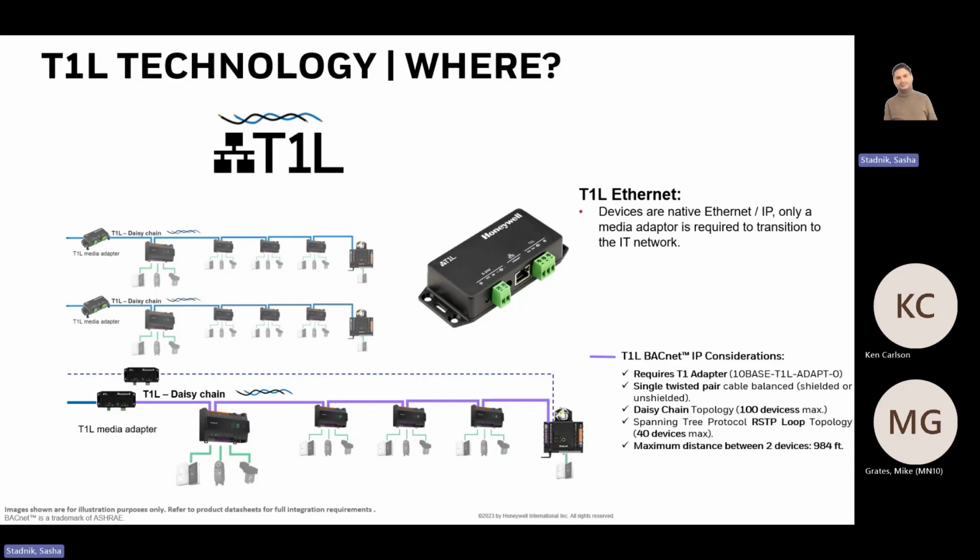Questions regarding T1L? One thing to note on that thing, if you look at it real quick, it says 24 volts. It's DC. Yeah. It'll take AC, but it won't work. No, it won't work. Does it blow it up? From what I hear, yes, correct. It will blow it up.